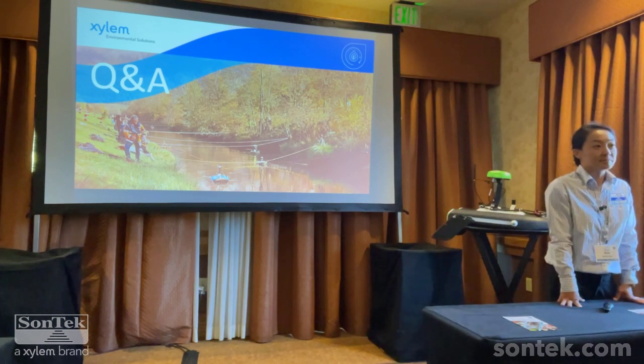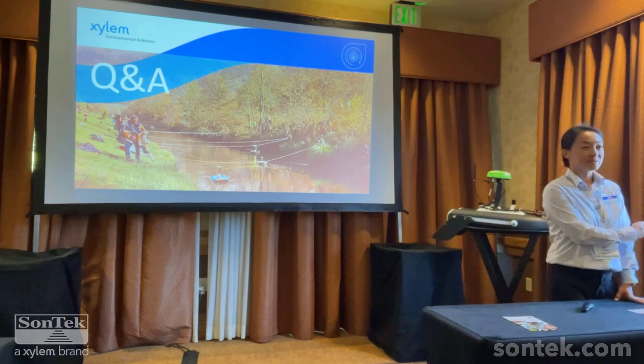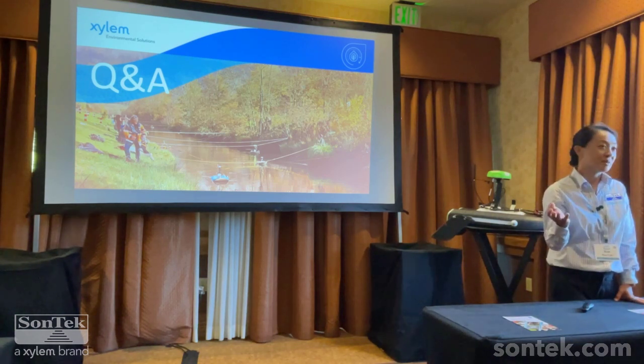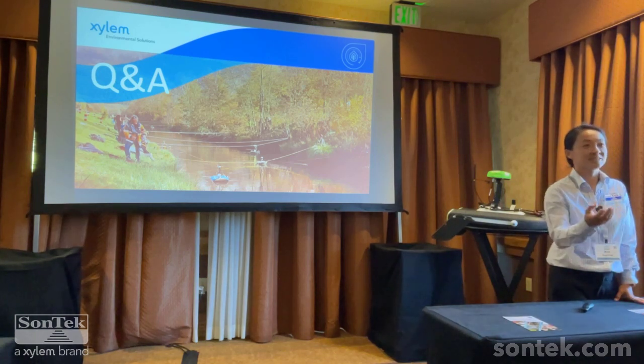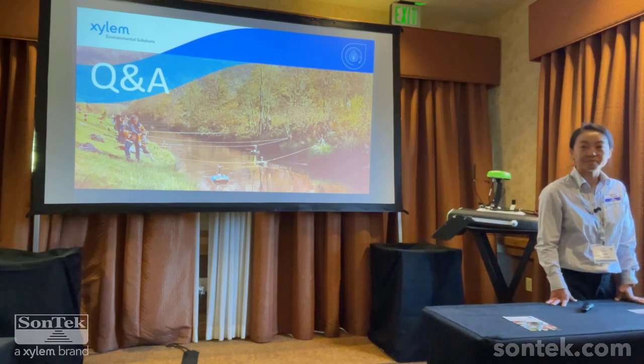use it during the winter, during the storms, and then some of the surveyors could go out and use it to catch some bathymetry where the channel bottoms are changing. Yep, absolutely. The nice thing about doing bathymetry with an acoustic Doppler current profiler is that you actually have velocities as well. So not only are you mapping out what the bottom looks like, but you can get fluxes of stuff and flow. So it's a nice all-encompassing tool.